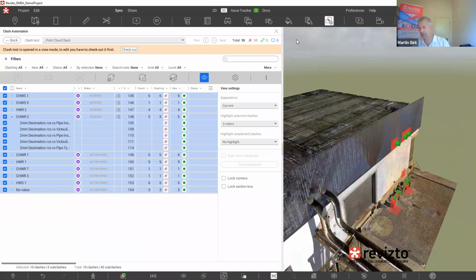I think the question is, in general, how do we actually link up to the model, and how is that updated? Yeah, so if you're using a tool to push the drawings in, I'll use Revit as an example. In Revit, you're pushing the sheet into Revisto. What it's doing is using the coordinates of the sheet to locate it in the coordinates of the model. So that's how it understands the XYZ positioning of it. So it's done like that.